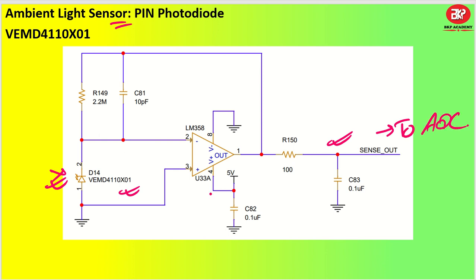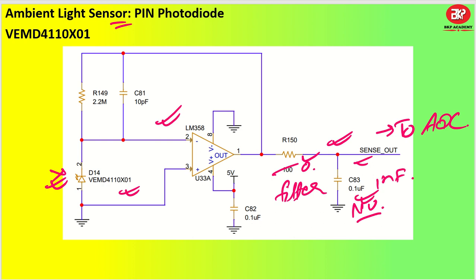So what is the thing that you can do here? One op amp that you can take up, which will buffer and amplify the signal and give you the output. And this is my filter circuit, which is 100 ohm and 0.1 microfarad. If you want, you can reduce this to 1 nanofarad as well. And if you don't want a filter, you can put this as 0 ohm and you can proceed, and this will not be utilized at that time. Got it? But I'll recommend you give the filter. This is suggested. At the same time, you can utilize the op amp, which will help you out.